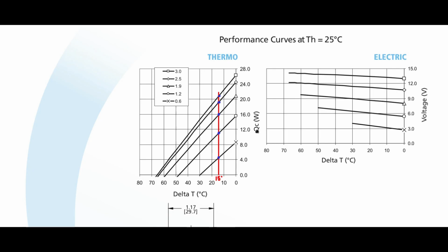Now QC is another design spec, because QC is the amount of heat that the Peltier junction will have to remove from the cold junction, and in this case the cold junction is the component which is dissipating heat. So the QC we said in the previous example was 20 watts. Now let us say 20 watts you want to consider removing from the component, pass it on to the heatsink.